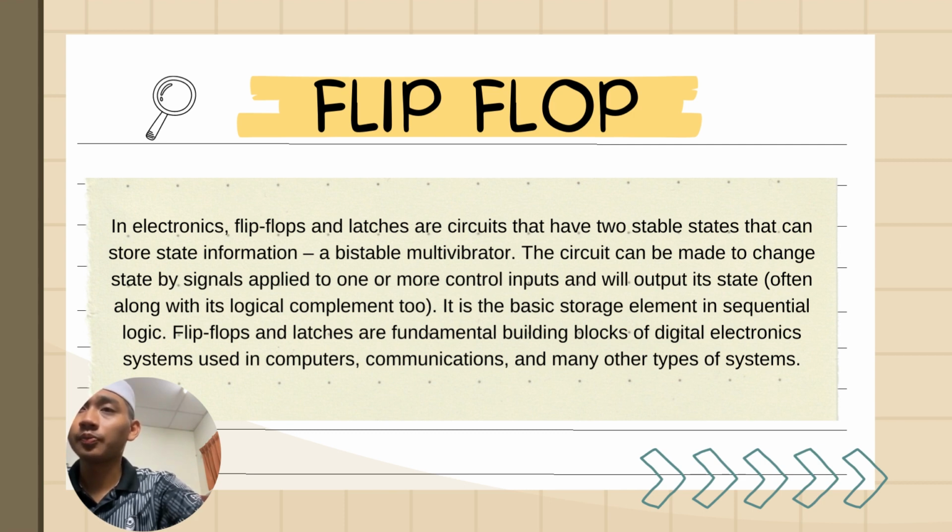Firstly is flip-flop. In electronics, flip-flops and latches are circuits that have two stable states that can store state information, a bistable multivibrator. The circuit can be made to change state by signals applied to one or more control inputs, and the output will often come along with its logical complement. It is the basic storage element in sequential logic. Flip-flops and latches are fundamental building blocks of digital electronic systems used in computers, communications, and many other types of systems.